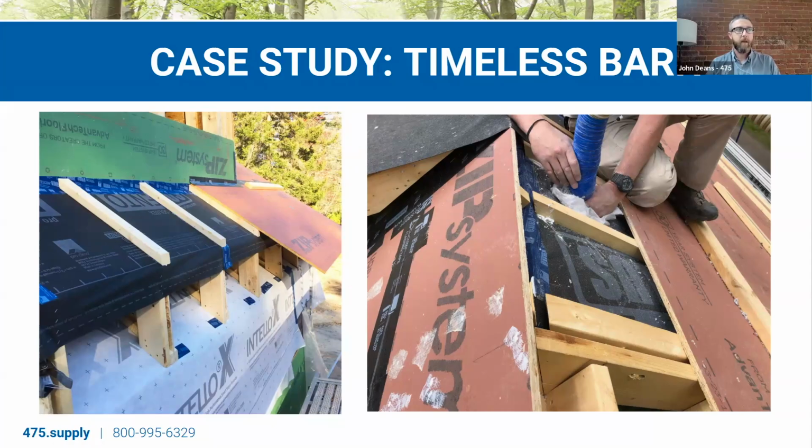The reason we did that is it gave us the ability, if we had an issue with the dense packing and needed to get the insulation machine in the middle of the roof, we could have. We didn't end up needing to use it for this, but something to think about if you're doing this assembly. We just basically left the tape off the ZIP sheathing, which again was fine. If there was a little bit of leaks in a rainstorm, it's just going to hit the Mento Plus and drain out. So again, we're watertight.